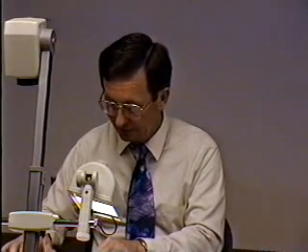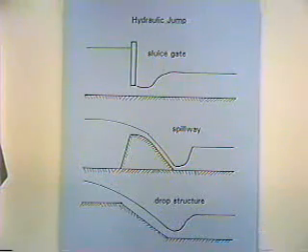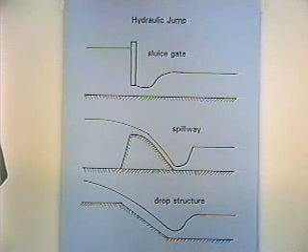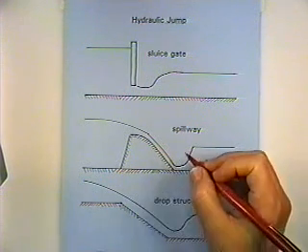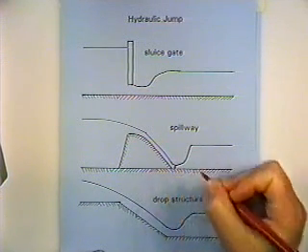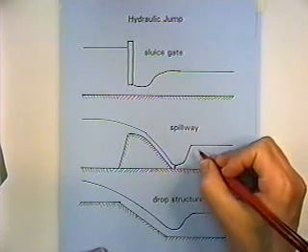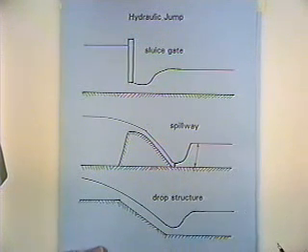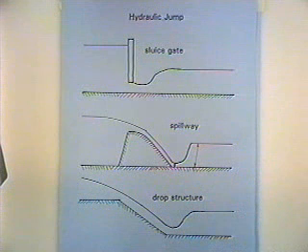If we take just a moment here and go back to this page of the notes, let's say we do a couple of things. We can use any of the hydraulic jumps we want. Let's go ahead, we just did some work with the spillway. Let's say that we do the computations we just did. We computed that depth, and having computed that depth, then we use conservation of momentum to compute this depth. And it came out like so.